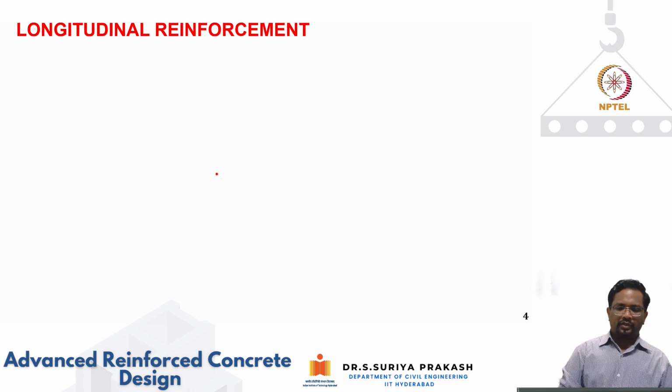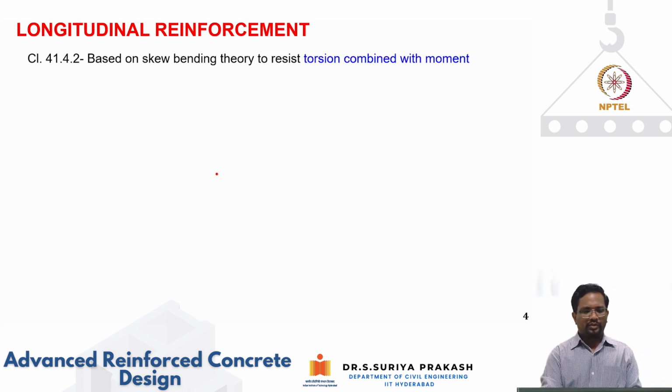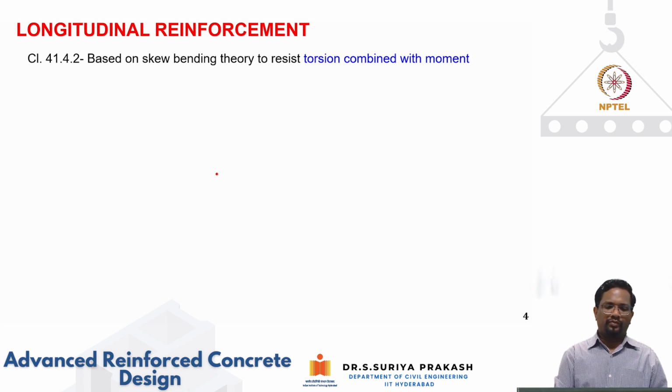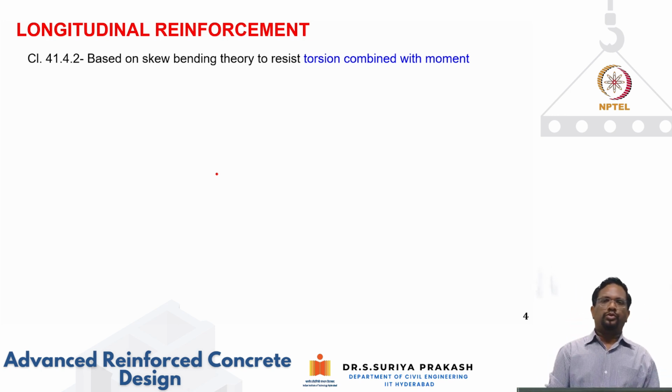Okay, right. So let's see longitudinal reinforcement. This is clause 41.4.2. It was developed based on the skew bending theory that we discussed. You remember we had talked about three failure modes: mode 1, mode 2, and mode 3. Mode 2 is a lateral bending failure mode, mode 3 is a negative bending failure mode, and mode 1 is a modified bending failure mode.